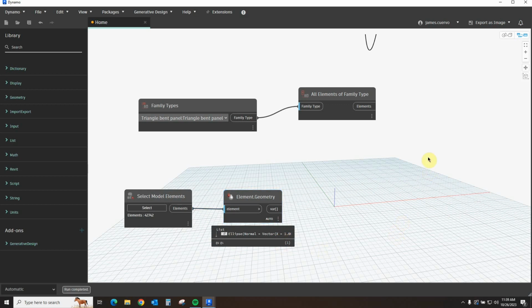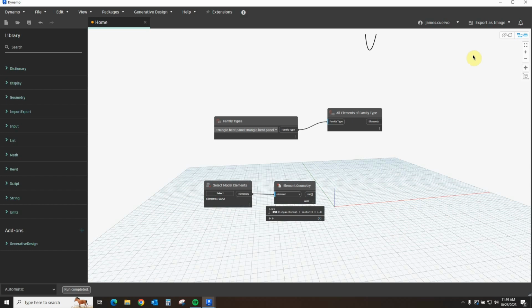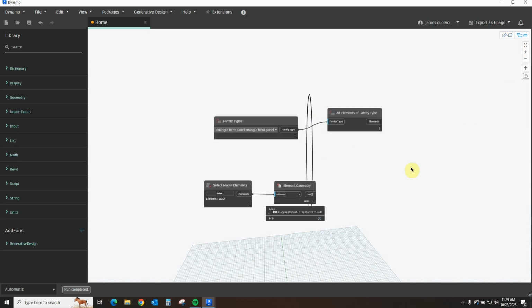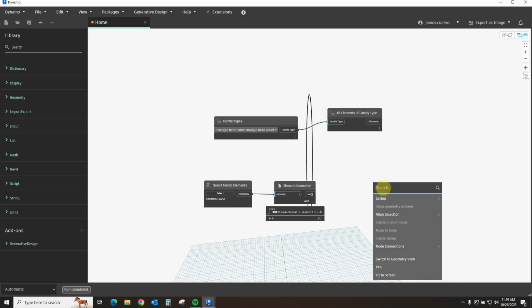To convert this shape that has now been brought in, let's come here and say zoom to that. That's my shape. Okay, let's go back into the foreground. We're going to grab that shape that has now been brought into Dynamo from Revit and turn it from a shape to a patch or surface by using the parameter surface by patch, which is right here.